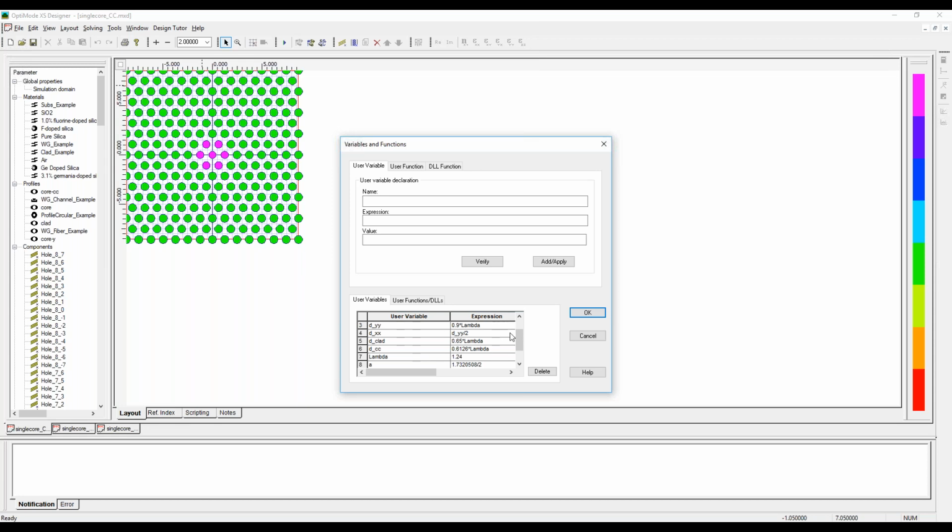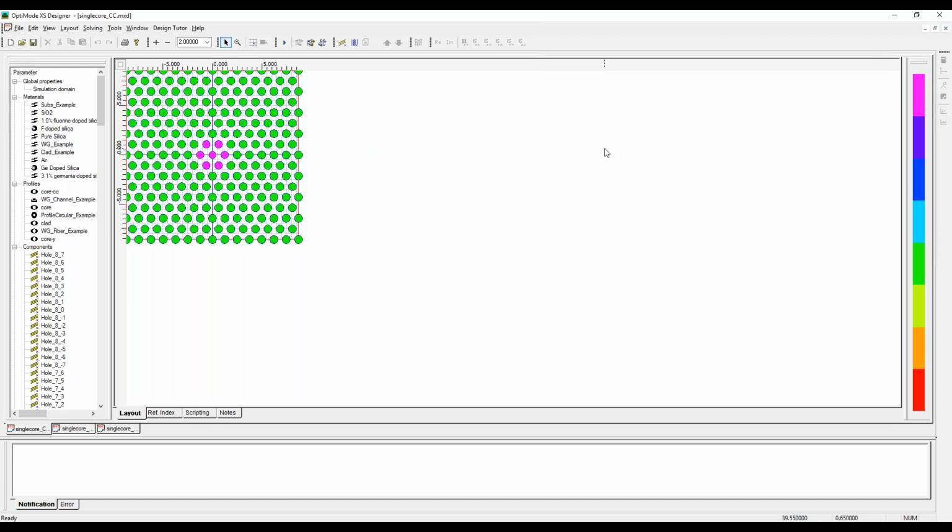And this is, if you want to do a really good simulation, a very complicated one like this, and make sure that it's very easy to use for simulating different things like the diameter, length, and so on, you want to script it and use user parameters. You could make so many mistakes if you were going through this and trying to change things by hand, right? So it's smarter to use a script and to use these variables to set up your geometry that way. I really suggest, once you have a simulation working and you want to sweep something like the diameter or the length of something, always use variables and a script. It makes, in the long run, everything so much easier.